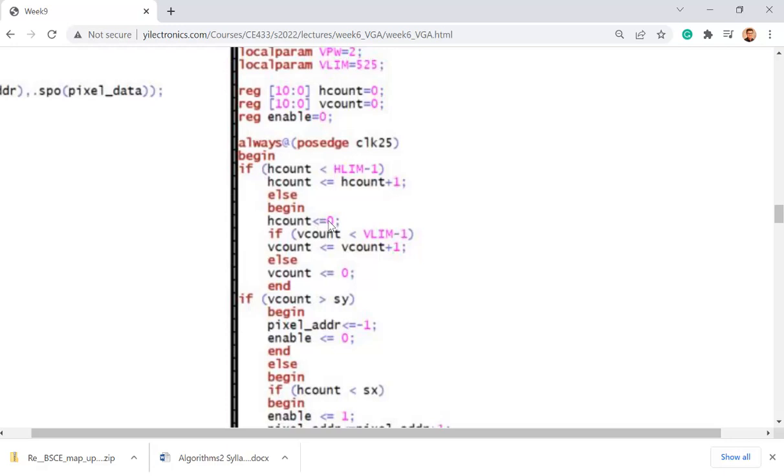All right. And if the vertical count is not reaching the vertical limit yet, add 1 to itself. Otherwise, just reset to 0. It's just like keep scanning to here. If it's reaching 800, then reset. Otherwise, just keep adding. Right. So that's the overall counter setup.